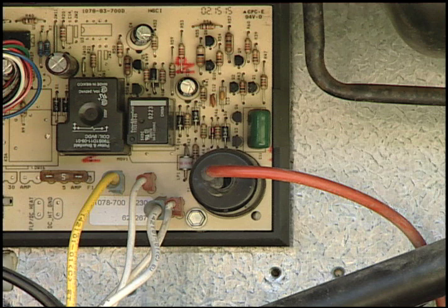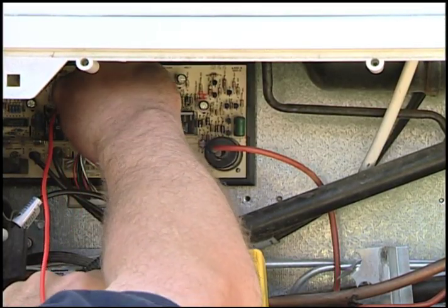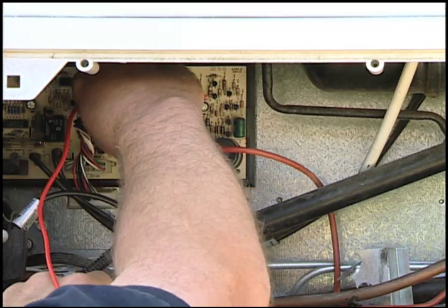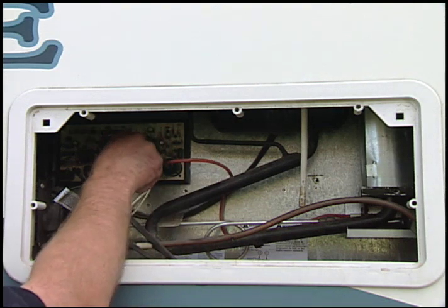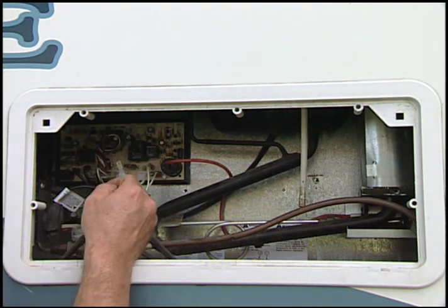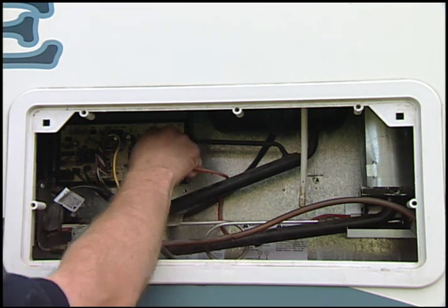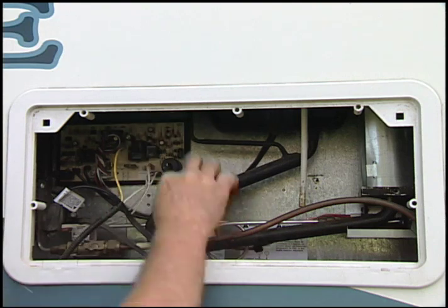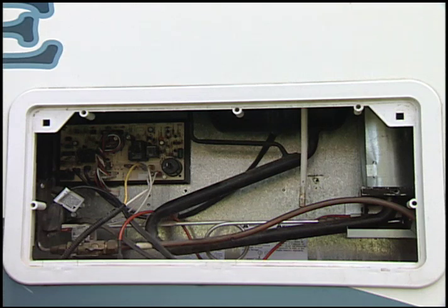To test the igniter, you must first verify that the 12-volt DC power is within 1 volt of the supply voltage at the main power block during the trial for ignition phase of the starting sequence. A drop of more than 1 volt indicates a loose connection or a circuit board problem. Next, disconnect the DC power at the main 12-volt power block. Remove the high voltage cable from the igniter and reconnect the 12-volt DC power. The refrigerator will go into a trial for ignition phase of the starting sequence, and you should hear a sparking sound coming from the igniter block. If not, you will need to replace the igniter.